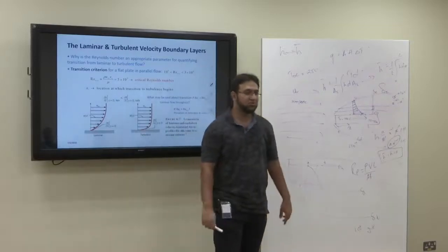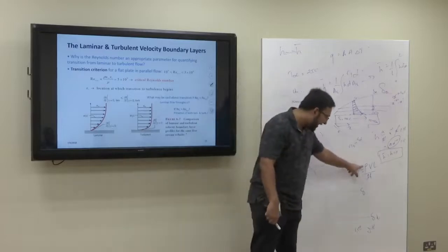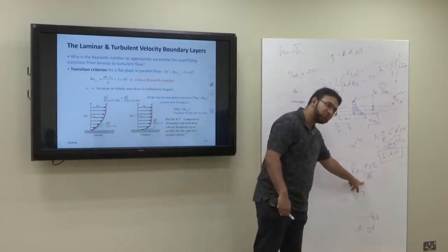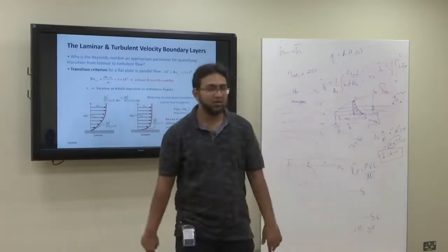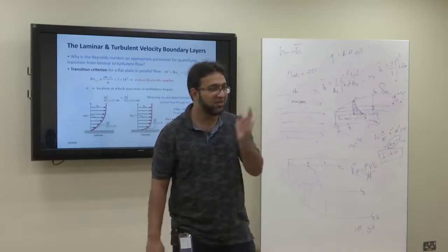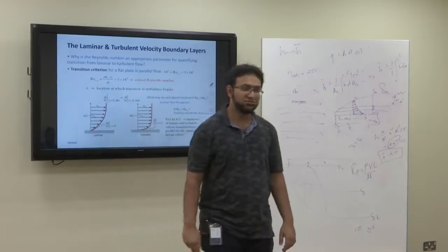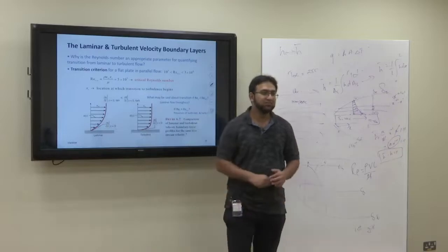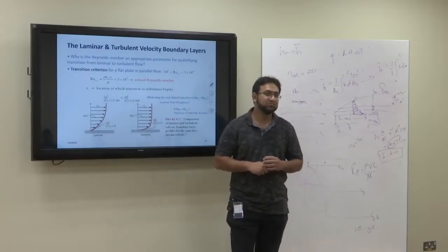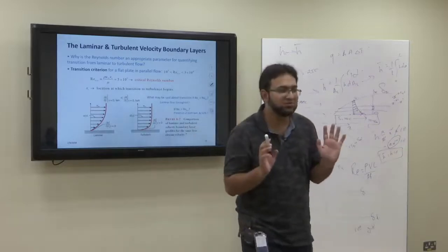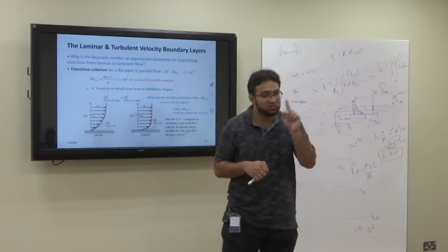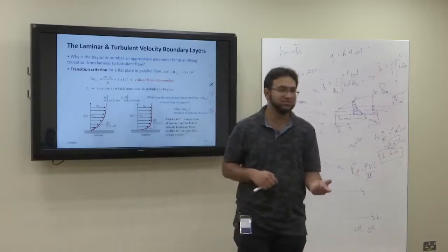It's not just the velocity you have to consider, the weight and the viscosity. Okay, the lava that comes out of the mountain, moving very slow, but it is highly turbulent. It's not laminar. You said before that you're interested in the turbulent, but you need the turbulent which is very fast, or the velocity is high? We need turbulent, irrespective of what's the velocity, because it is the turbulent which increases the heat transfer.